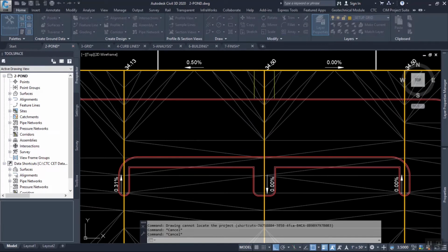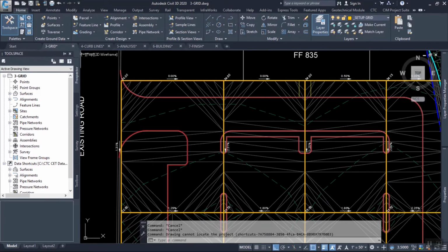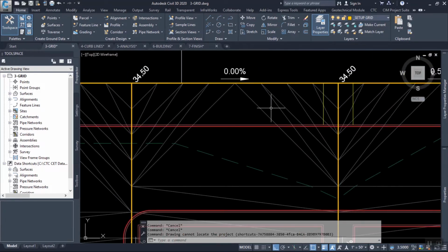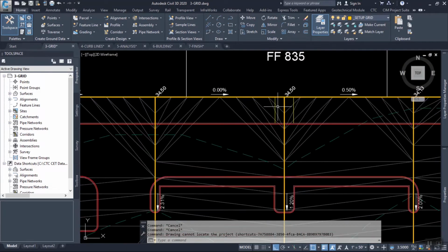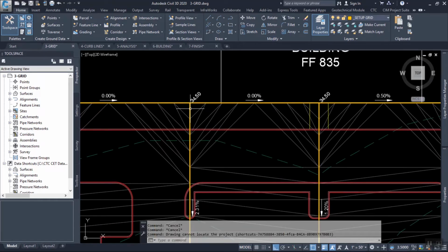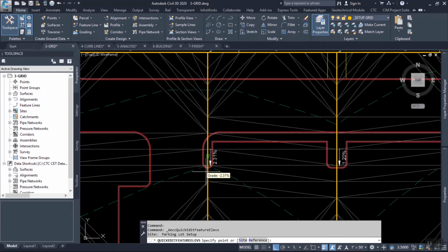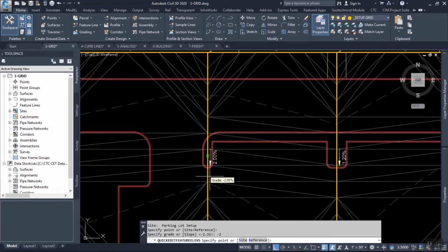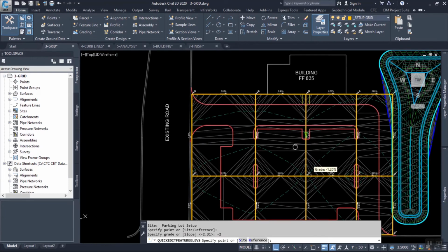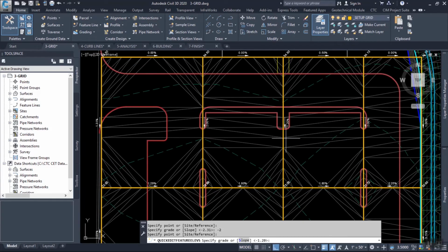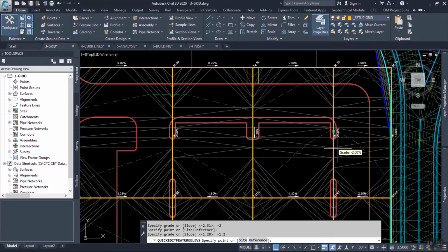All I've done is I've gone through Quick Elevation Editor and I've started making edits to those where I started making decisions. Well, I'm assuming the building's here and we're coming here and we're sloping down at a negative 2%, okay? And that's going to be my low point. Up here we're coming down, and I might not even know, it's just preliminary at this point, okay?